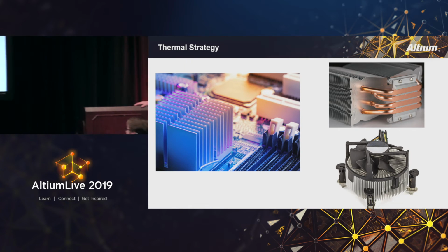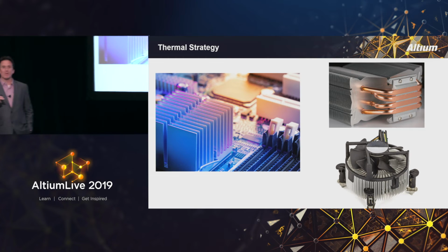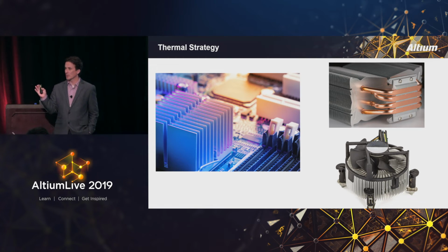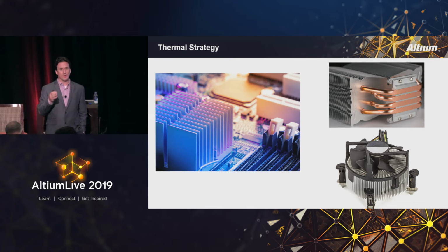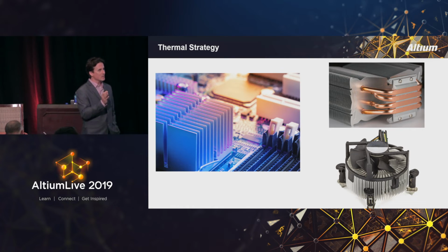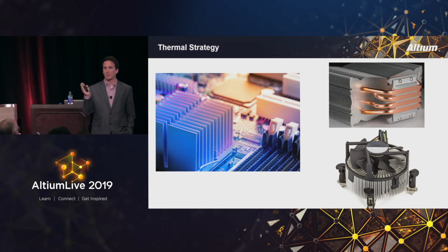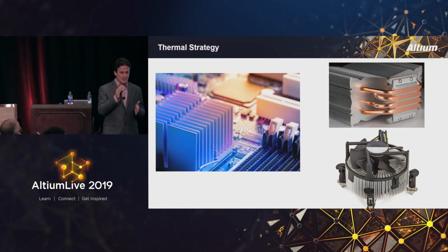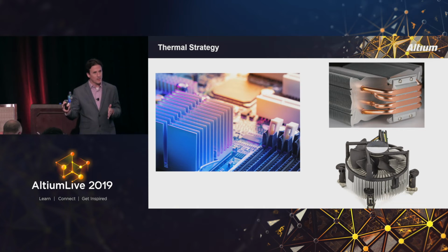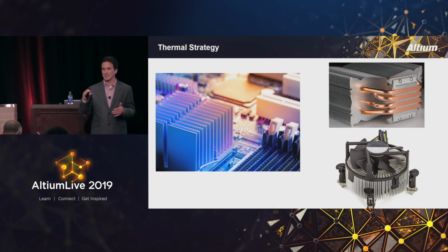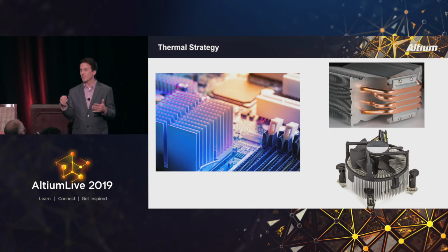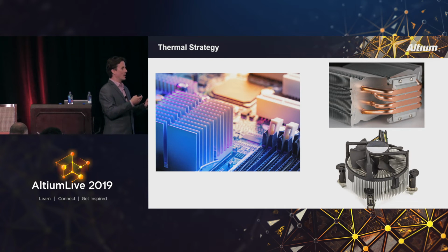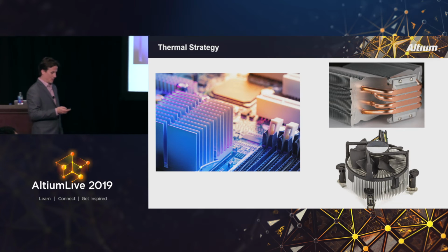One tip that I would give at this point is just because you don't have a fan on your device pushing air through it does not mean that you're not going to have airflow. So one of the other things you have to think about, even if you're using passive cooling, is lining things up with your heat sinks so that they permit airflow. Don't just do something haphazardly, because as soon as heat starts getting generated in your electronic device, it's going to start creating convection airflows within it, and things should be set up in a way that capitalizes on that.